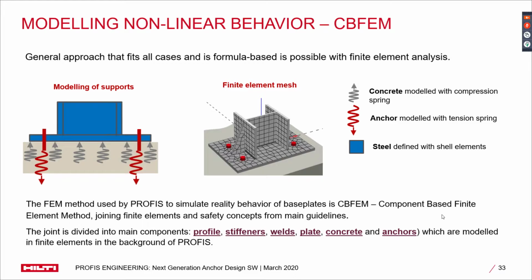As mentioned, in order to model the realistic nonlinear behavior of our connections, we use component-based finite element method. CBFEM individually models each connection component and connects them all together in the global model. We model the concrete as compression springs. The steel is modeled with 2D quad and tri-shell elements with a bilinear stress strain curve.